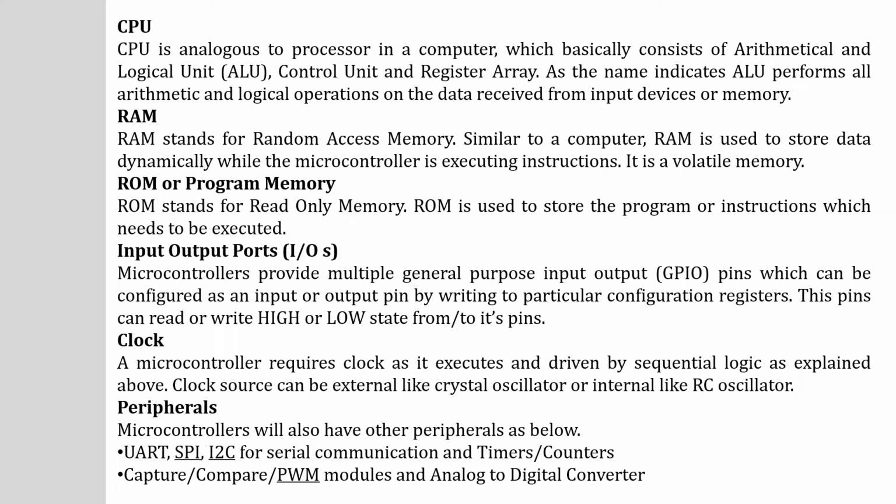And next, coming to the input-output ports. A microcontroller provides multiple general-purpose input-output pins, which can be configured as input or output pins by writing to particular configuration registers. These pins can be read or written to high or low states.